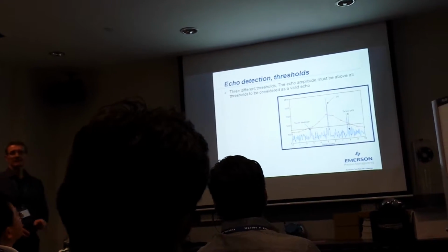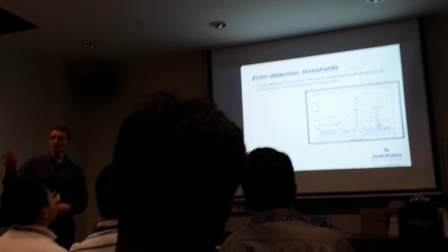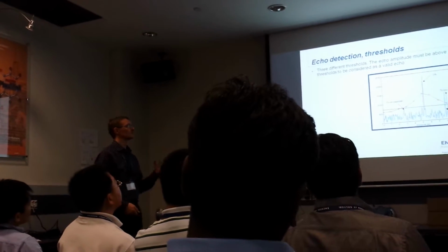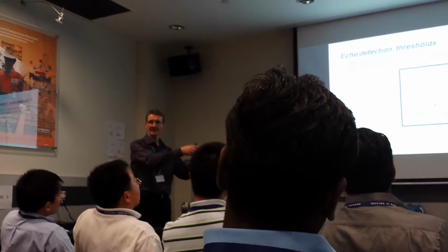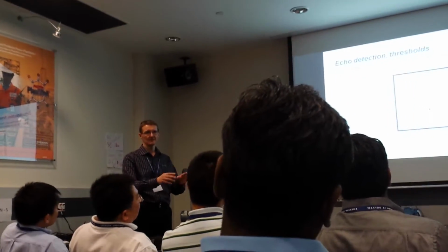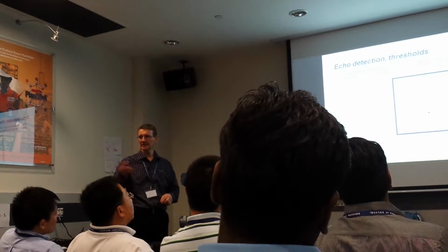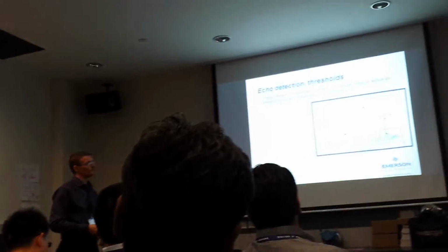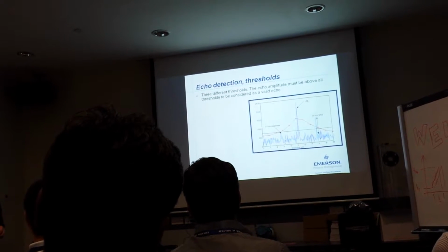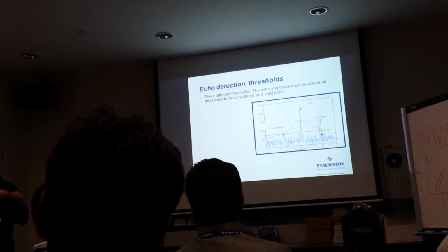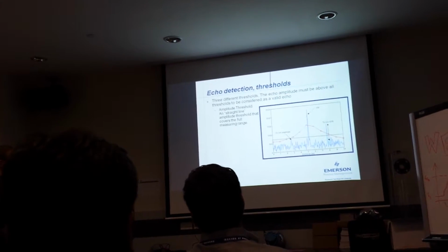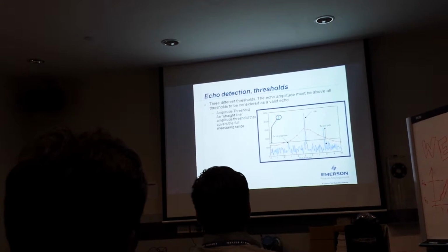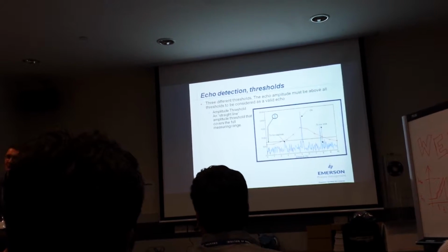Okay, so the gauge found many echoes, maybe in your opinion too many echoes. So then you can ask yourself, how can I improve the situation for the gauge? I mean, it's your input, maybe for the gauge. Say that, okay, we have to adjust a little bit. So what can you adjust? Well, we can look at some basic things. If you have looked at the tank scan, you have, for example, the blue line, the threshold. It's black here, but it's blue in setup.